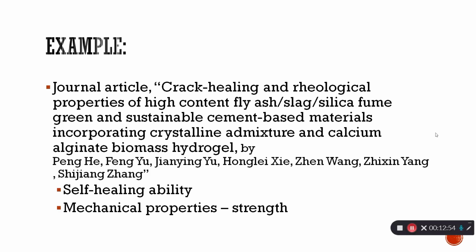The tests that were observed focused on the mixture proportion specimens and cracks that developed in the cement. Water permeability amounts, crack measurement and width were taken, along with mechanical properties, and crack healing for self-healing performance of cement concrete. The cylindrical specimen was then split to further observe the crack that developed and healed.